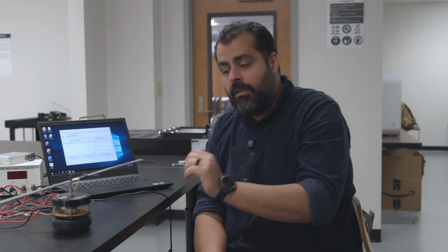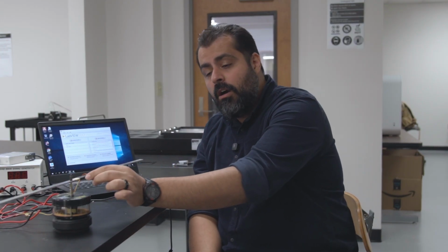The idea is that when you provide a frequency, any frequency should be fine. We are probably going to use lower frequencies so we see a higher amplitude, which essentially means a higher strain at this specific location. Again, the idea is to create a vibration here, and this vibration is going to cause a strain in this direction, a displacement in this direction on the beam.